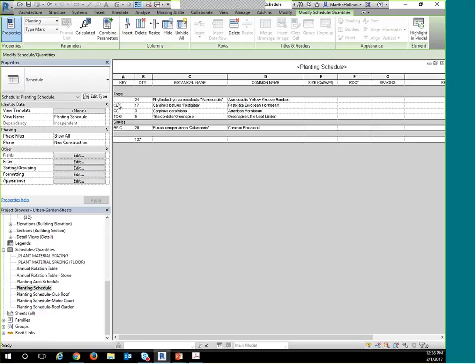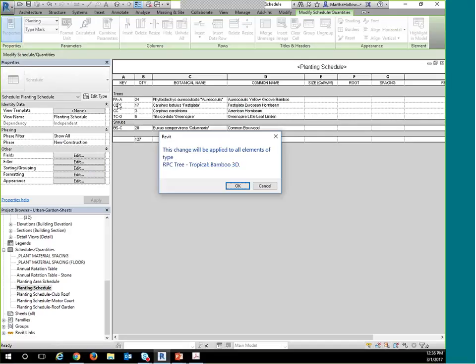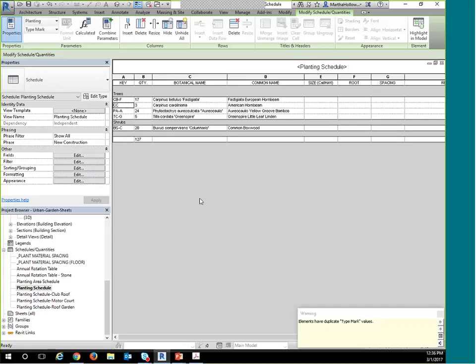And also here, this doesn't have a key. So what I need to do is add one. If I do it here, PA-A, this is going to change all of these that I just put in. And now there are some duplicate type values. I'm not going to worry about that. But anyway, that gives us the information that we need for that as well. So that's just a little power of the BIM, the whole BIM or landscape information modeling as well. When you are dealing with your schedule, you can make sure the right information is up there and going.